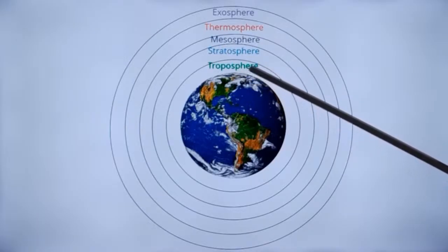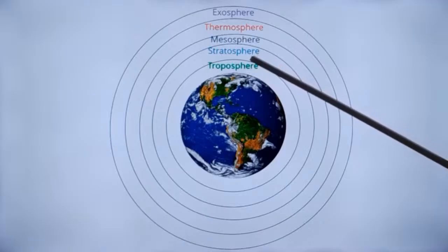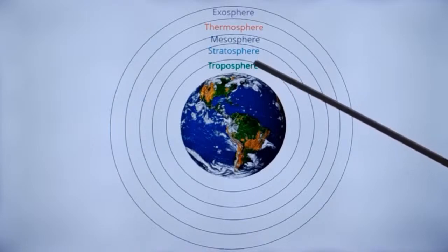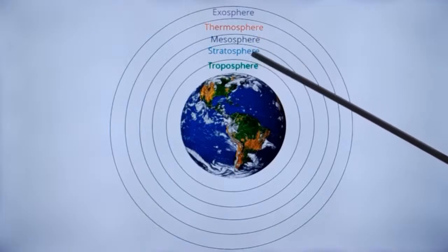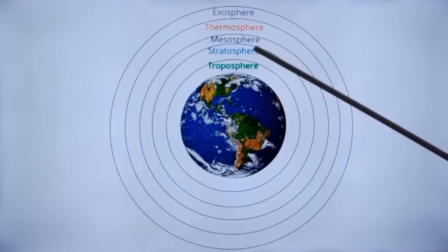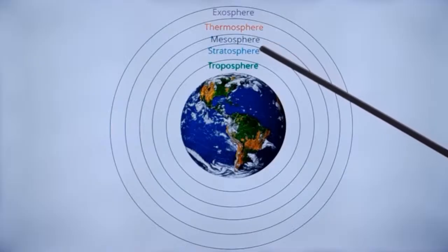At daytime, there is more ionization. At night time, ionization is less. Similarly, when the solar activity is more, with more of sunspot activity, ionization increases. Currently, we are in solar cycle 25 and we are reaching the maximum in another 1 or 2 years. When the maximum is there, ionospheric condition will be better for long distance propagation and you will have more ions in the ionosphere due to solar sunspot activity.